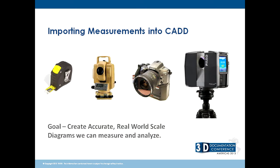Importing measurements into CAD and into our program in particular, again, our goal is to create accurate real-world scale diagrams we can measure and analyze. How do we do that? Well, over the years, tape measures, baseline and triangulation, total station, cameras using photogrammetry style programs and importing that data, and now laser scanners. All these methods are still valid. You still might use the laser scanner and still need to go take a couple of measurements with your tape measure at some point, or combine total station data.